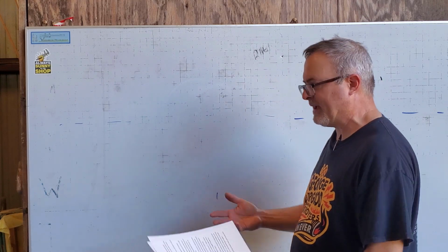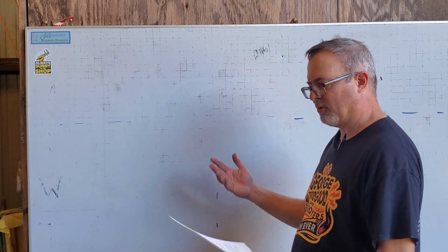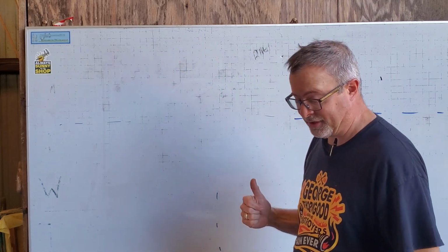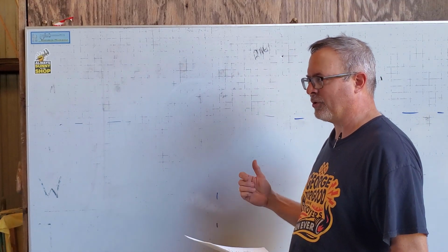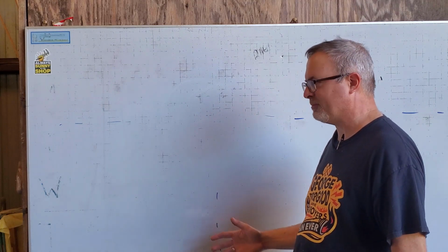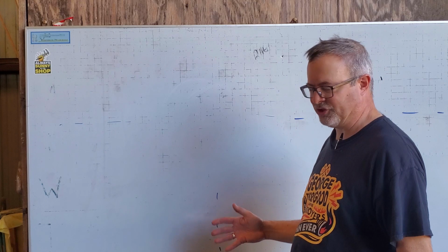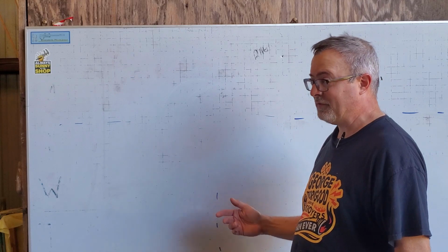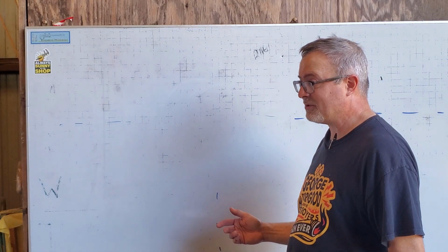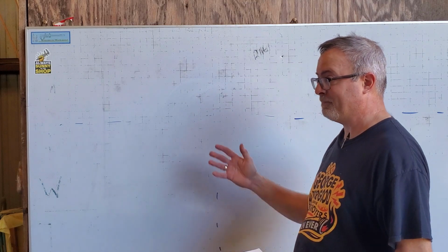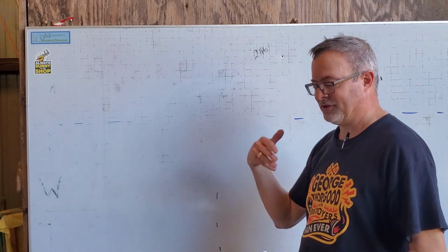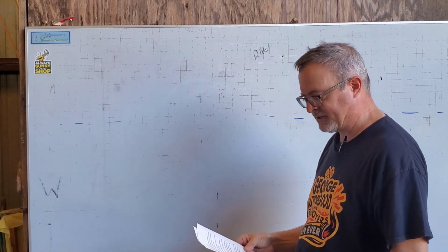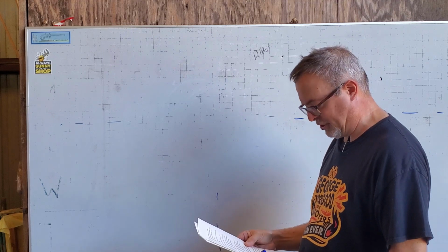It's a trade-off. How much mass is there in the frame of the engine itself to absorb all this? For a single-cylinder horizontal reciprocating diesel engine, the recommendation is that the foundation block that the engine is attached to should be 3 to 5 times the mass of the engine. So in the case of the Skinner engine, you're talking a 5,000 pound engine. So 15,000 to 25,000 pounds of mass in the concrete to help absorb the vibration that the 80-some pound mass of the reciprocating system generates. That's what we're looking to do.